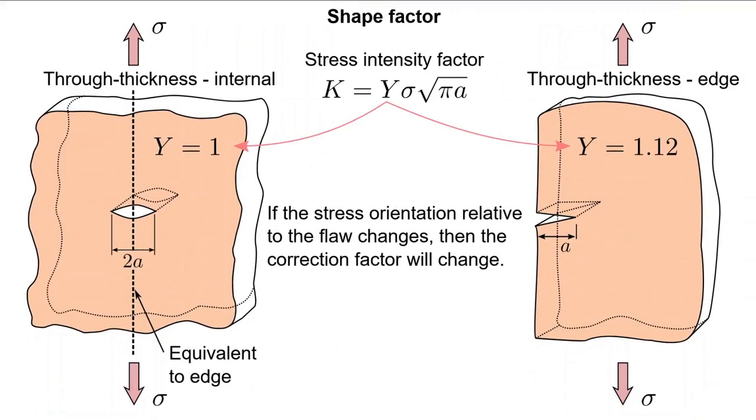Before we're ready to start applying plane strain fracture toughness, we need to clear up one small detail: the constant Y, which turns a proportionality between stress and the crack size into an intensity factor. The true nature of what Y actually does is beyond the scope of this course, but for now you can treat it as a constant.